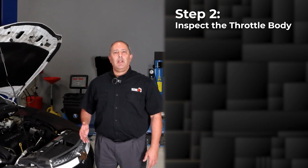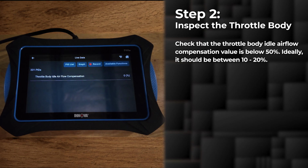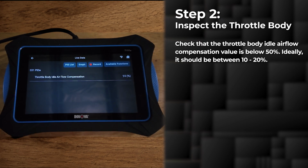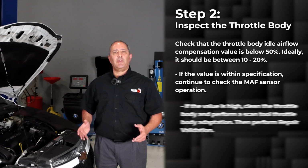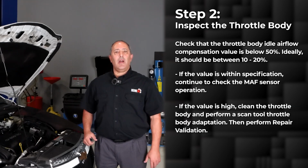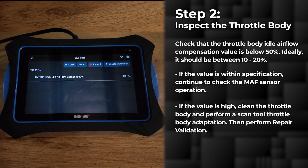Step 2, inspect the throttle body by checking the idle airflow compensation value. It should be below 50%. Ideally, it should be between 10 and 20%. In this case, the value is within specification, so move on to the next step. However, if the value is high, clean the throttle body and perform a throttle body adaptation using a scan tool. Then perform the repair validation.